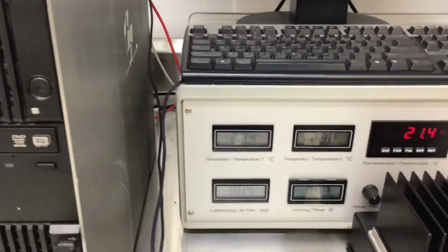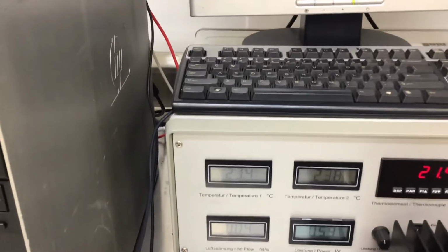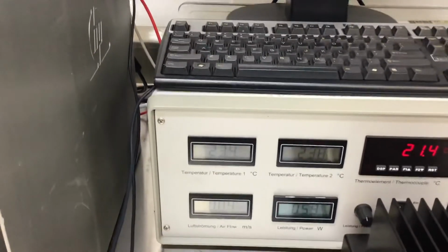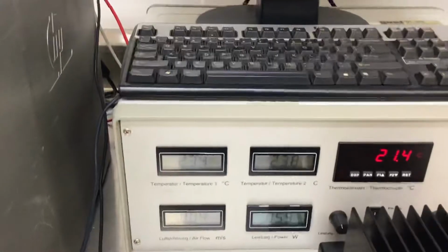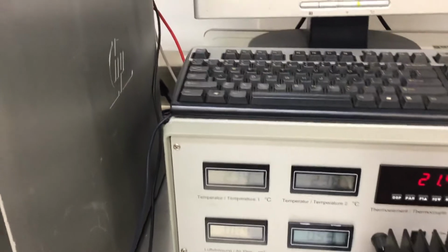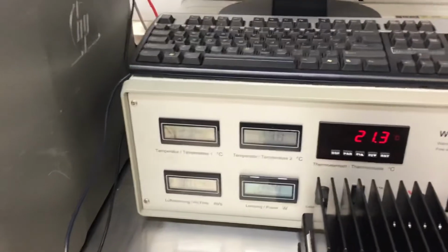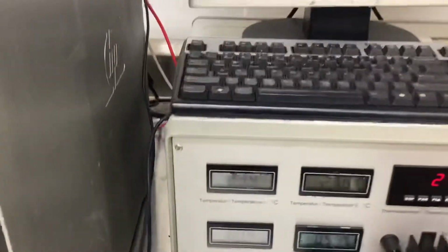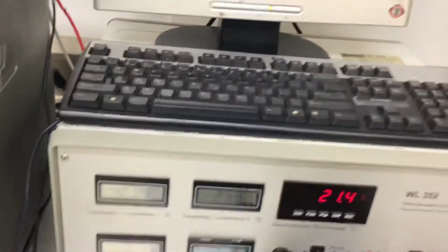You have to wait until it gets to steady state. You monitor the temperature to eventually get to a steady state, and then you can use the equations that are meant for a steady state. You will have all the equations explained in the lecture part of this experiment, but we still have one major measurement that is needed for this experiment to be conducted, which is the thermocouple measurement.